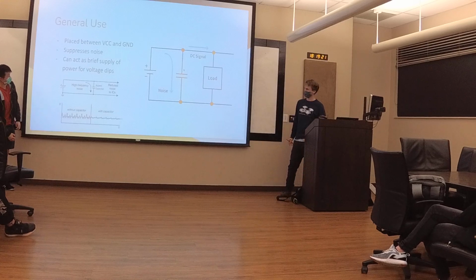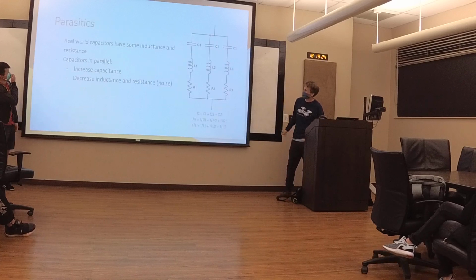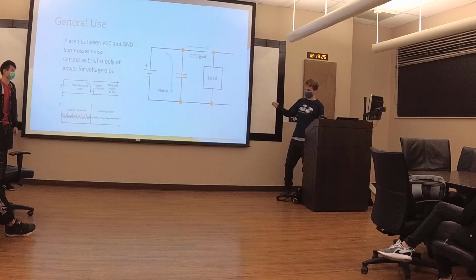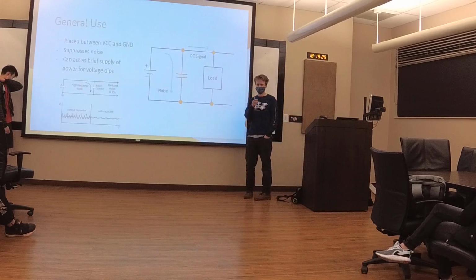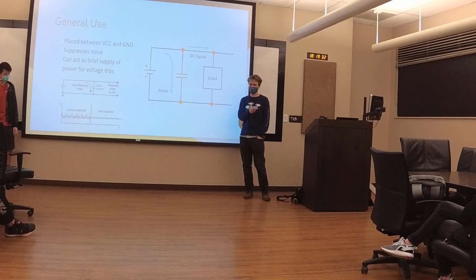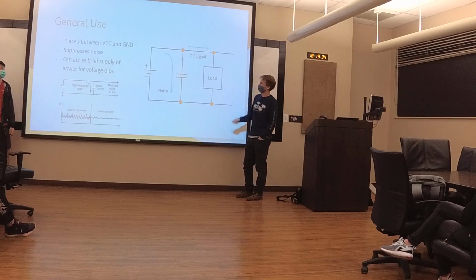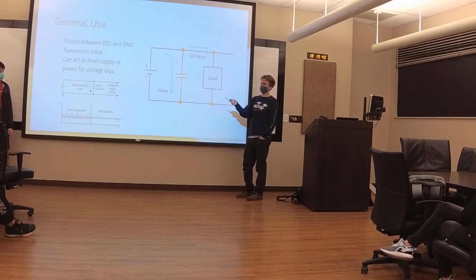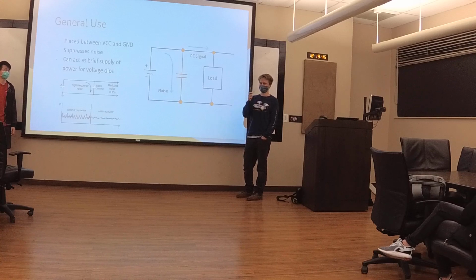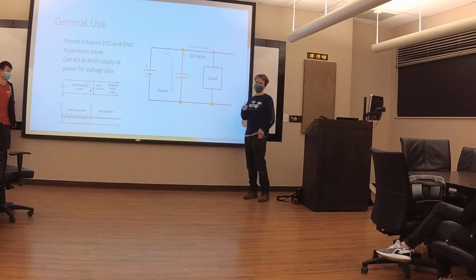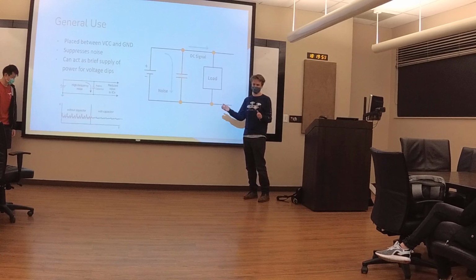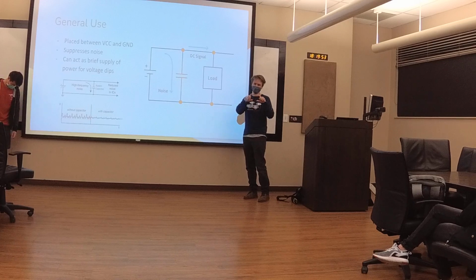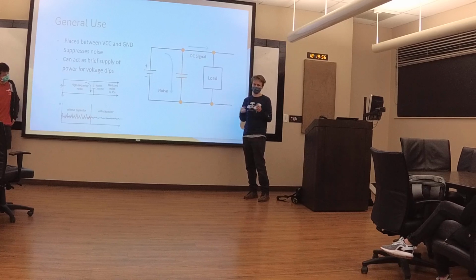If the next slide doesn't cover it, I want to go back a slide actually. I'm going to quickly introduce you to a little bit of physics. If you've taken AE3 here, you definitely know what impedance is. The impedance of a capacitor is 1 over j omega C. You can think of impedance as complex resistance. Like with a resistor, you have Ohm's law, V equals IR, which is pretty simple. With impedance, you make it V equals IZ.